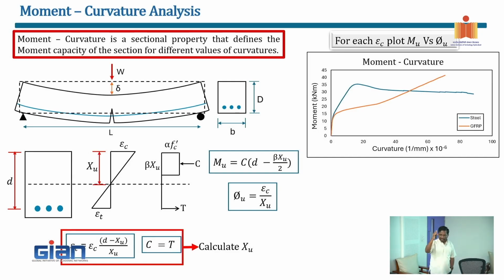If you put the same cross section, same strength, same amount of rebar, the slope of the GFRP section is going to be much lesser than that of steel. So I can compare all these things. From the ultimate strength point of view, absolutely there is no issue, but EI, the flexural rigidity, is much lesser for the GFRP section. That means typically in a reinforced concrete member, what will be the level of service moment compared to ultimate? Can you take a guess?